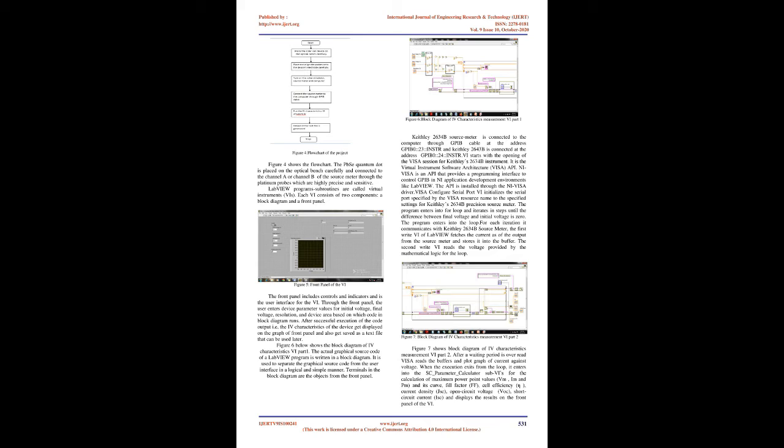A Class AAA solar simulator from Keithley Technologies, PECL01, was used to provide the illumination intensity of AM1.5. A shadow mask was used in front of the device under test, DUT, to match the illuminated area closely with the device area. Current voltage measurement of the device was carried out with a Keithley 2634B source meter under ambient condition, integrated with LabVIEW for monitoring and processing the data.